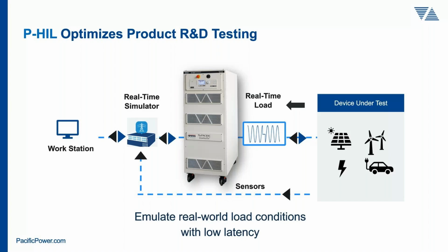They all offer this HIL real-time interface, very commonly used for renewable energy microgrid simulation applications, where the hardware of the load or the power source is used to simulate real-time events using the simulator, and the signals are going into the unit in analog signals typically, and the unit provides back 6 readback signals for voltage and current, so the simulator system can monitor the reaction of the microgrid to the stimulus that is being applied. So very commonly used these days in high-end simulations of microgrids.